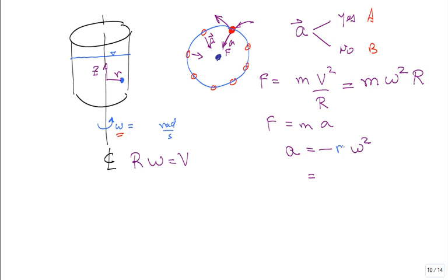Right. So what we can do is get an expression for the pressure in the fluid. We already mentioned that the pressure contour looks like this. So anywhere along this line, is the pressure the same? And if I drop down, is the pressure the same anywhere along that line? And then, yeah, it's got a parabolic, a quadratic shape to it. So we have the pressure as a function of r and z.